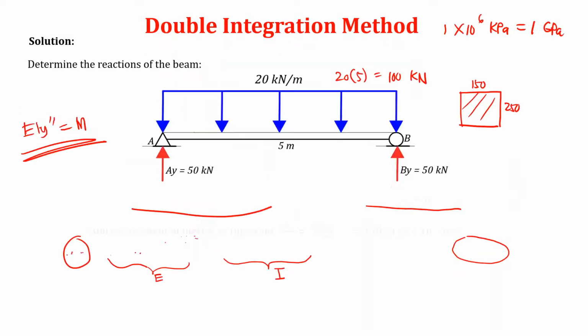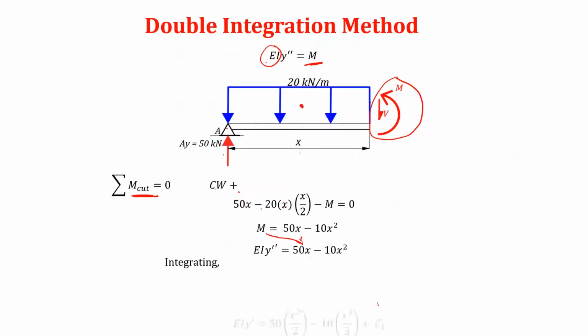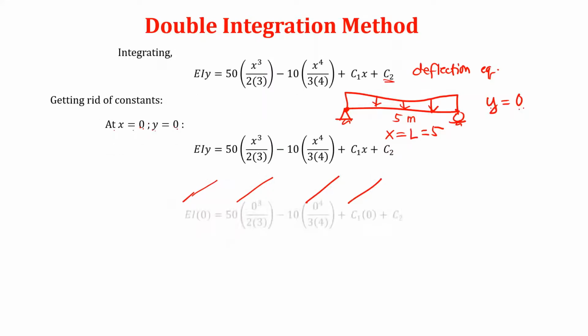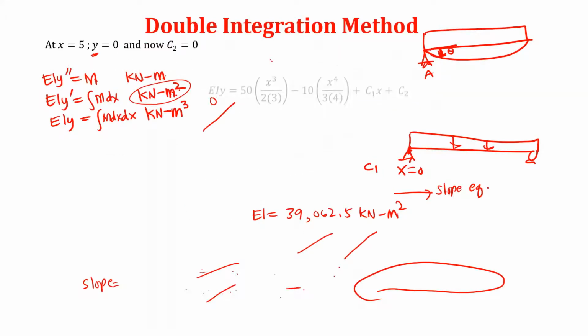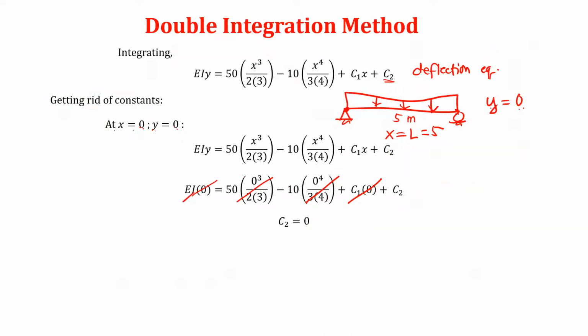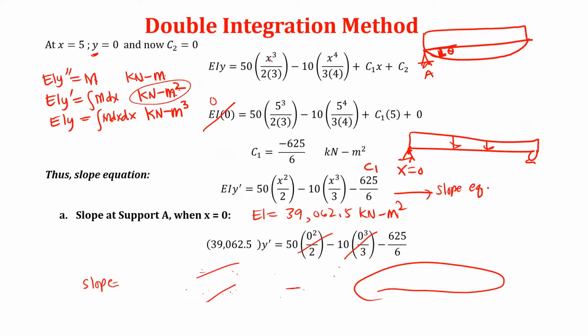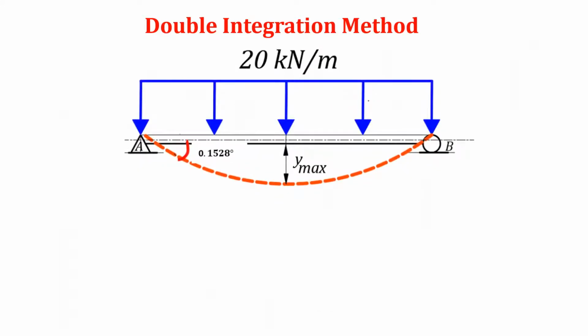Okay, as you can see, this is just a simply supported beam with a uniformly distributed load. So, if we are looking for the maximum deflection, where will it occur? You can see the figure, guys. Of course, at the middle, because there is no support there, unlike near the supports. The middle is the farthest from the supports, so that is the maximum, at the location when x is L over 2.